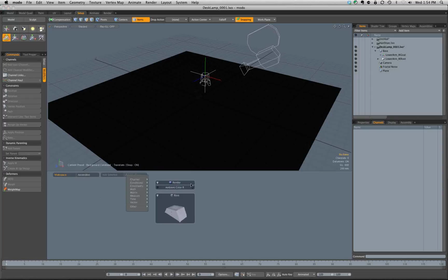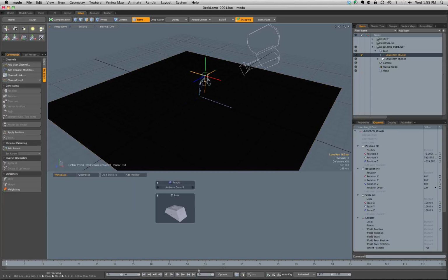It's pretty nice because you can add different modifiers. For instance, that claw I showed you earlier, the inverse kinematics claw. What can happen is instead of me animating two parts and setting up keyframes for two parts, I can actually set it up right in this assembly and then clone that rig and join it together. So rather than setting it up twice, I can set it up once and then just mirror it over.